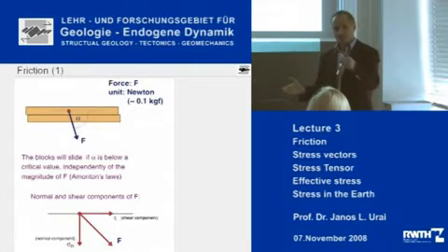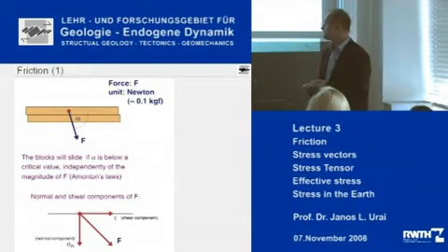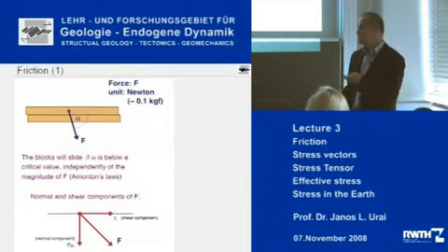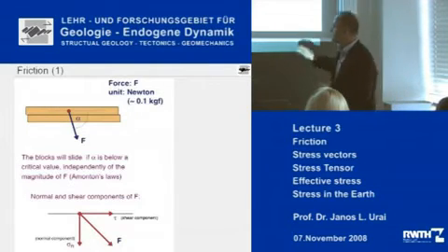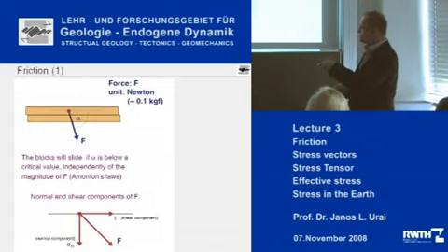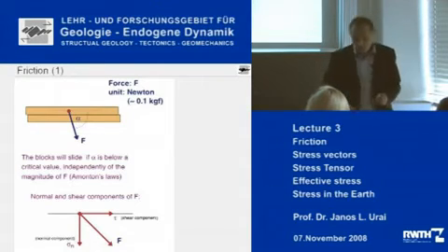The force can be big or small, it is the angle which determines whether you get sliding or not. And this F, or if you divide it by the area, then it becomes the P, the stress vector on the plane. It can be decomposed into a normal component and a shear component. We have seen that before.